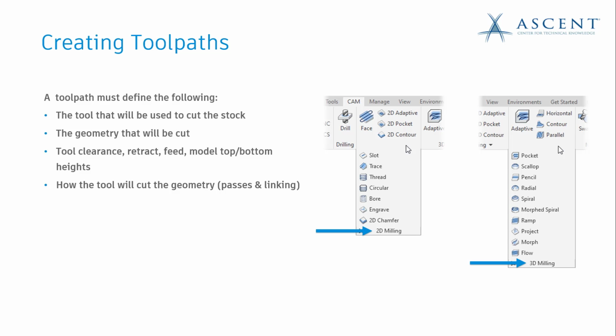3D milling allows for machining models with more curvature, contoured surfaces, more of those free-form type models, and therefore the references are more surface, faces, and edges on the model. In milling these contoured surfaces, specific roughing and finishing toolpaths exist as compared to 2D milling, where there are fewer toolpaths and the same type of toolpath can be used both for roughing and finishing based on how you customize the options inside of it.